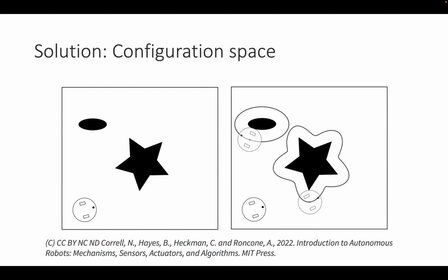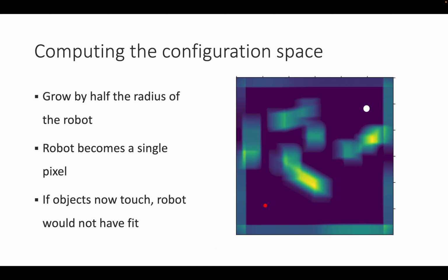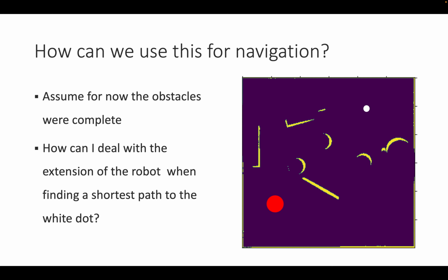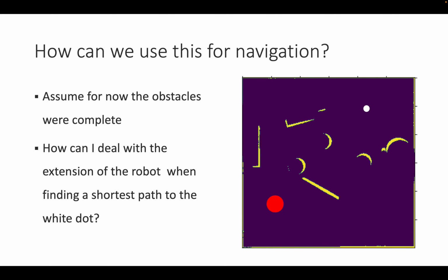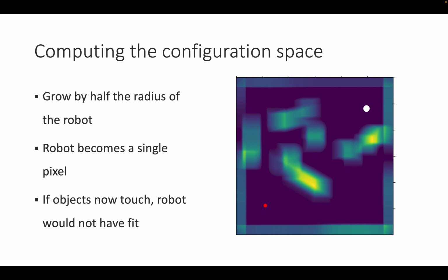So instead I propose to use something simpler, which is a simple blurring operation. And what I've done here is I took the map input that you see here and I blurred it so that all of the obstacles grow and eventually touch each other. And now I know that depending on how much I blur this, the size of the blurring operation can be a function of the robot disk size, and I can do that until I get a configuration space in which this passageway here is illegal, and I can know that everything I now navigate will be completely safe.